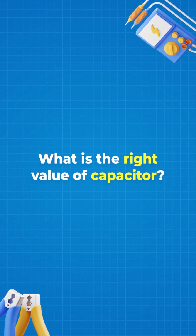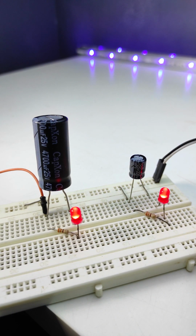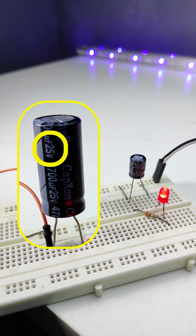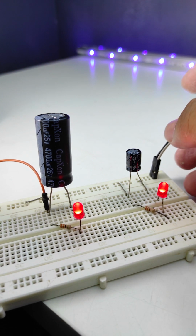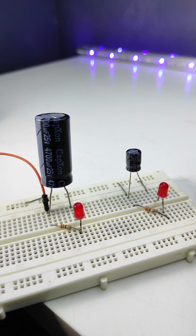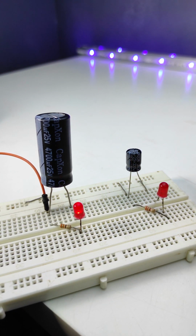Now, how are we going to know the right value of capacitor to put in our circuit? Here we have a 2 LED circuit. The first LED circuit has a capacitor with a value of 25 volts and 220 microfarads, while the second LED circuit has a capacitor with a value of 25 volts and 4,700 microfarads. Take a look at what happened on both LED circuits when I disconnected the 5V power supply. As you can see, the LED circuit with a 4,700 microfarad capacitor takes more seconds before it totally fades out, compared to the LED circuit with a 220 microfarad capacitor, which fades out faster.